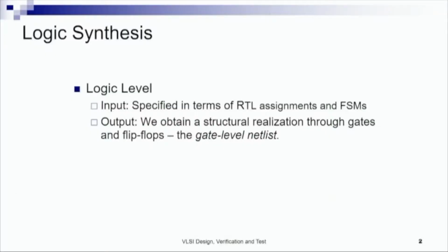The objective of the logic design or logic synthesis, on the other hand, is to obtain the micro level architecture of the circuit in terms of gates and flip-flops. So, the input to the logic synthesis step are in terms of the RTL assignments and FSMs. At the output of the high level synthesis step, we obtained a set of RTL assignments, register transfer level assignments, and we said that the controller FSM will control at which time step which of these RTL assignments are to be excited or activated.